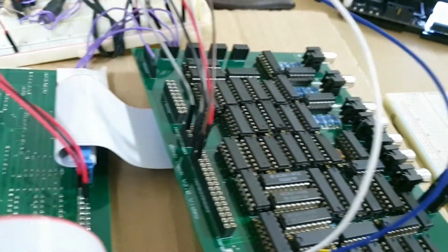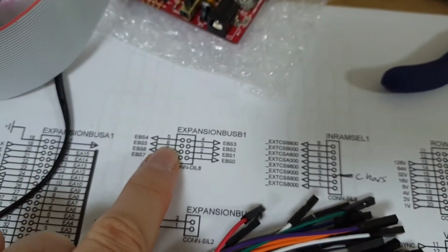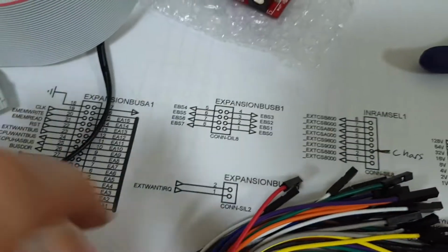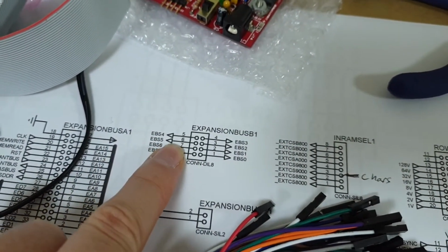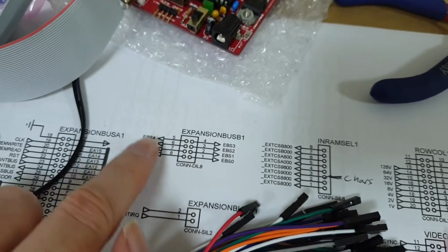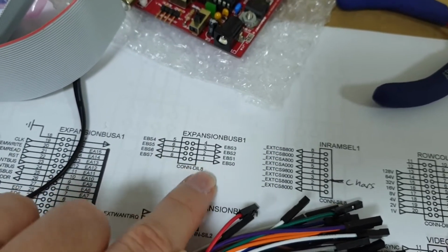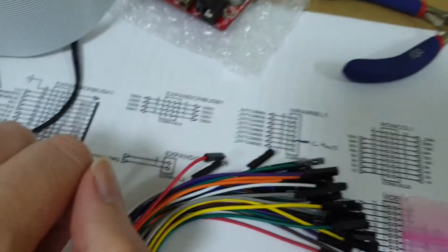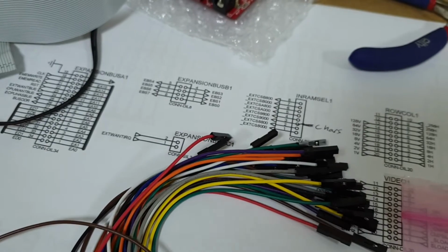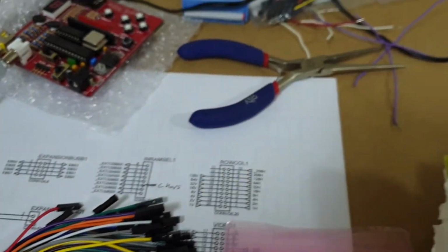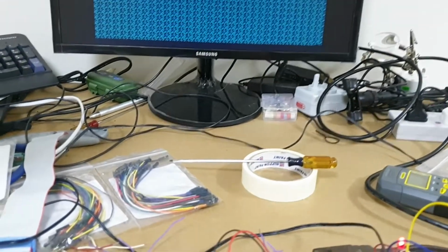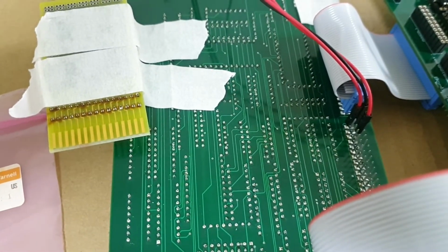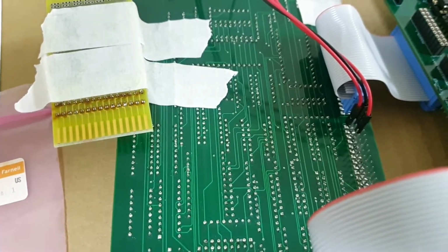this one here corresponds to, if I find the expansion bus debug information, that top left one, down one, so pin 6 on the header is EBS5. EBS5 is the high nibble, so 1, 2, 4, 8, it's 2, 0. This is 1, 2, 4, 8, but it counts up, and this is the low nibble, this is the high nibble. So it's 2, 0, and 2, 0 corresponds to the debug information, how the board was set up in the PCB layout tool to be extended memory bus address 20, which basically addresses all of the RAM for the character bit planes on this board.